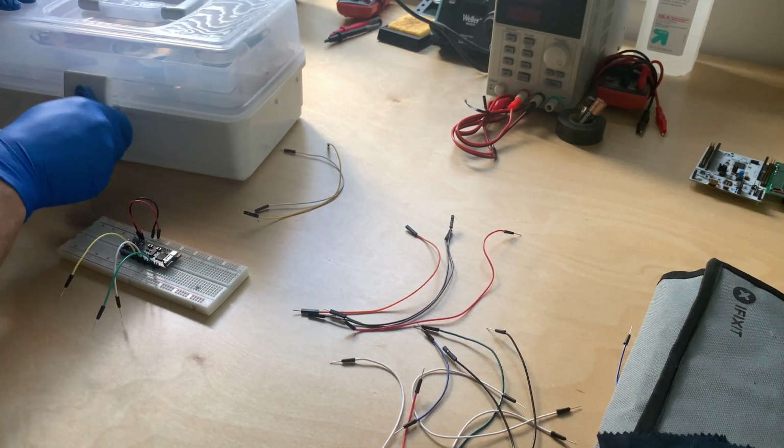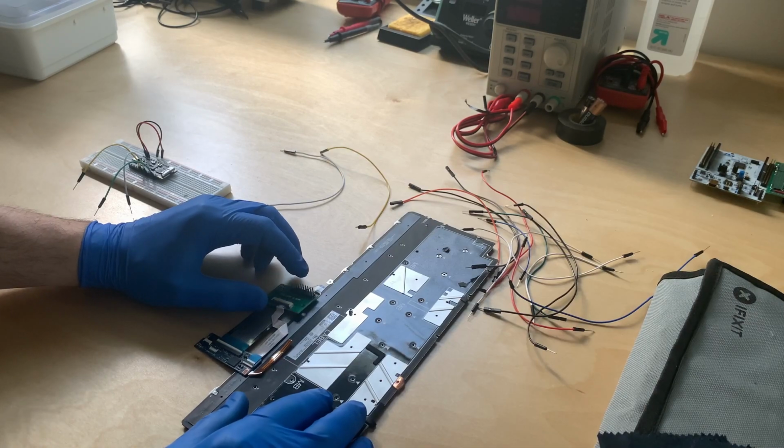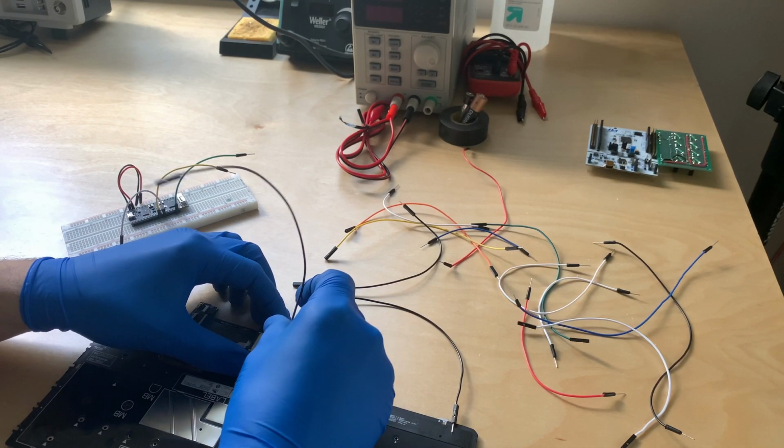If we can't see any signal when the function key is pressed, then we definitely know that there is no way to remap the signal anywhere in software or in any circuit above the keyboard, including any UEFI mappings.